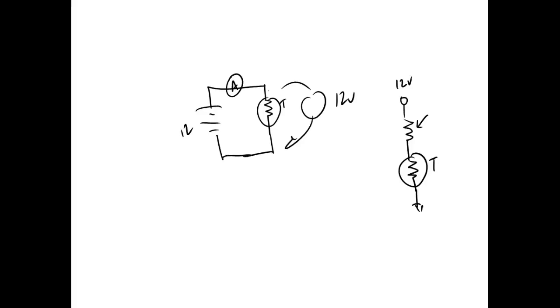You understand that? So if this is an NTC thermistor, when the temperature goes up, its resistance goes down, then the voltage drop across the thermistor would go down. Well, it's working like a rheostat, not like a pot. But you're not controlling the rheostat with a knob. You're controlling the resistance with temperature.